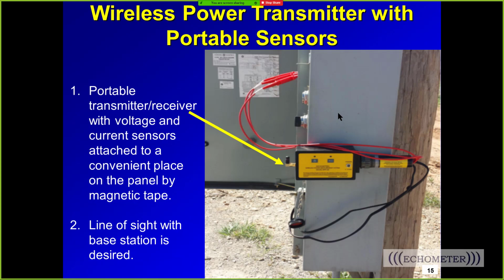So the wireless power probe reads the voltage and the amps and the kW, and we can use that information to see if the wire going from the pumping unit to the transformer is too small, and we're wasting energy by the cyclic loading causing current to flow back and forth between the wires. This is an antenna, and the antenna needs to see the base station that we transmit the data back and forth with, from the panel back to the computer in TAM.